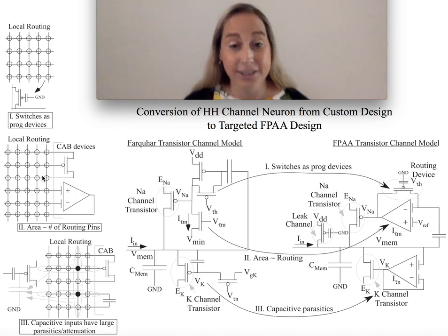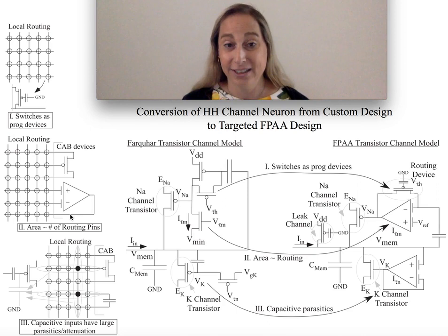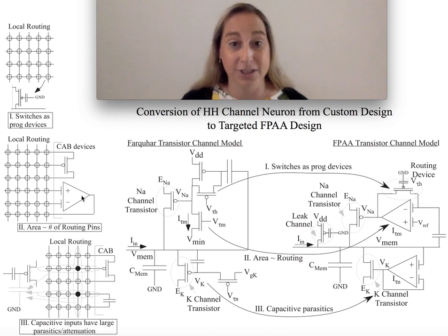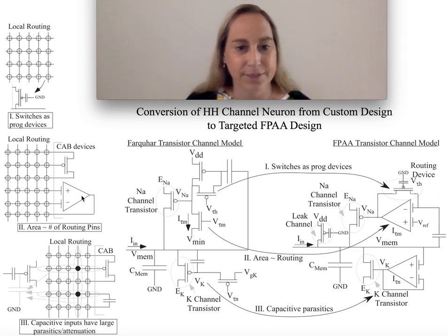The number of lines I need for a transistor is 3. On the OTA, it's again going to be 3. So they're about similar complexity, which is an interesting question because normally we'd think of this as 9 transistors plus other devices. But in a practical sense, it's not that much bigger. And so they're much more similar in this sense.